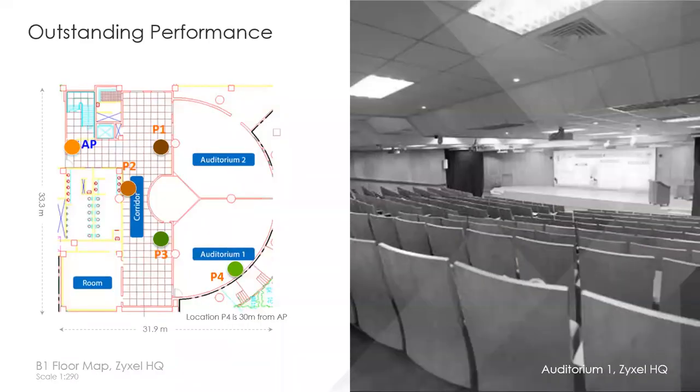So smart antenna is purely an AP-based technology. It does not require anything special on the client device. It will work with any client devices. And it also works with moving devices, unlike something like beamforming, which really requires very slow motion or no motion